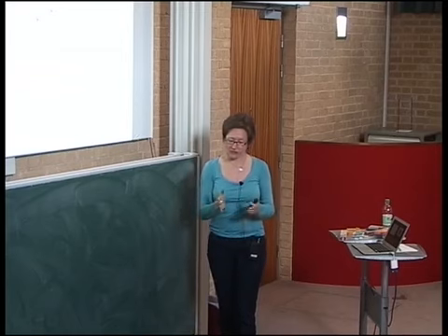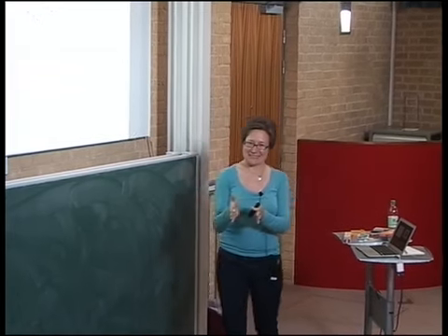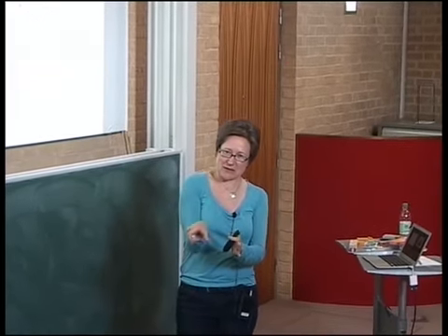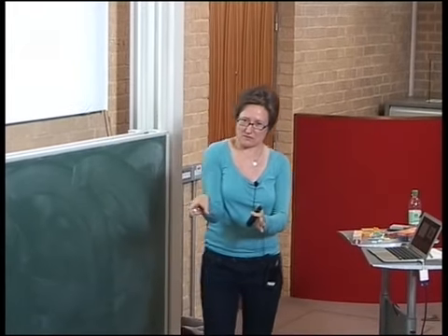And you may indeed get that, but if you've got any slight curvature in the flow device, what that tends to do is tip the high shear band to be near the inner wall and the low shear one near the outer wall, and you in fact then lift that degeneracy and only get 2 bands. You get a low shear and a high shear.